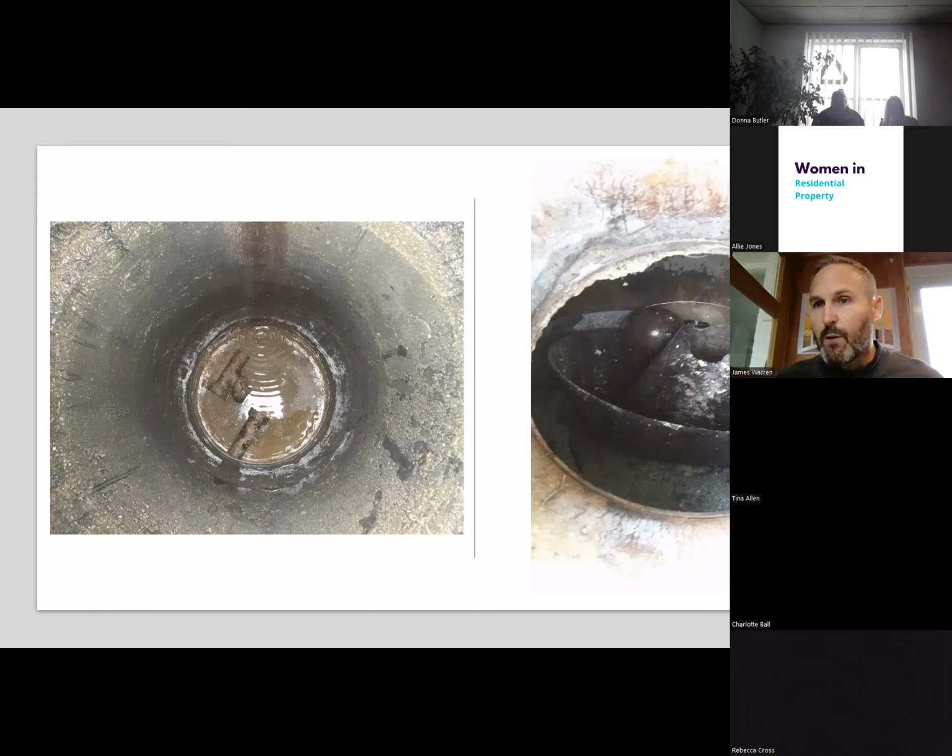In the olden days, soakaways were literally holes in the ground, backfilled with rubble and clean stone, and they actually worked very well. The separated wastewater would communicate with it. The biomass that grows in the sewage treatment plant naturally grows and occurs underground because air can get through the substrata at a meter depth. So underneath the soakaway is where the treatment occurs, before the water then goes under gravity, hits an aquifer, and gets away to the surface water.